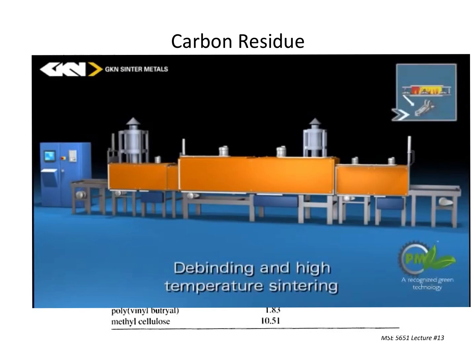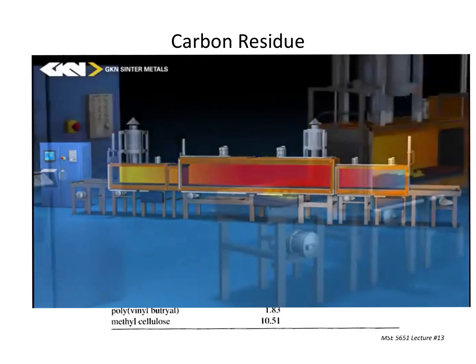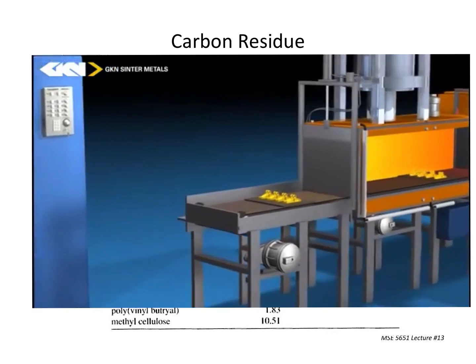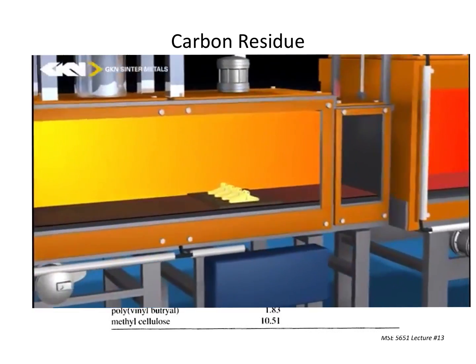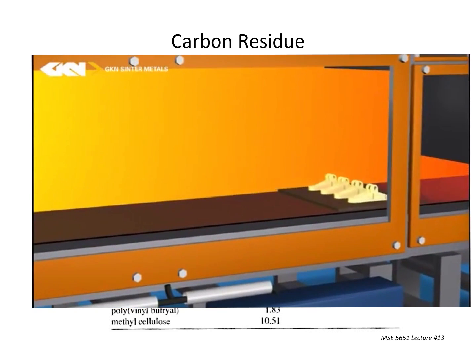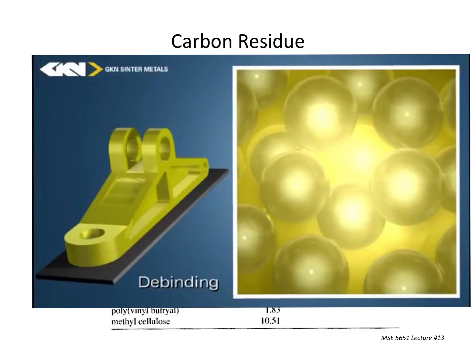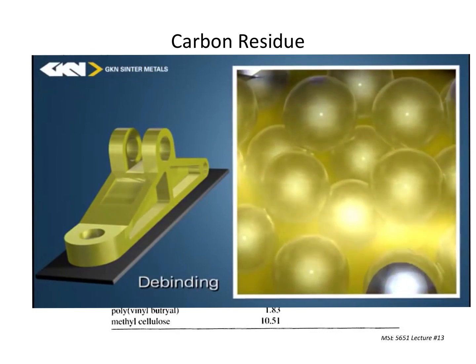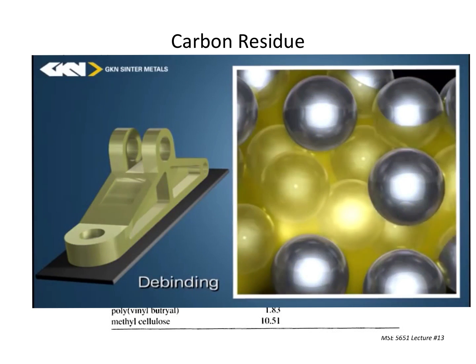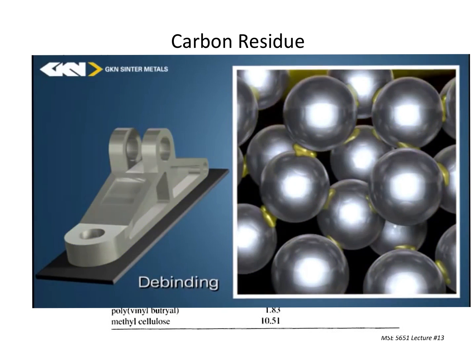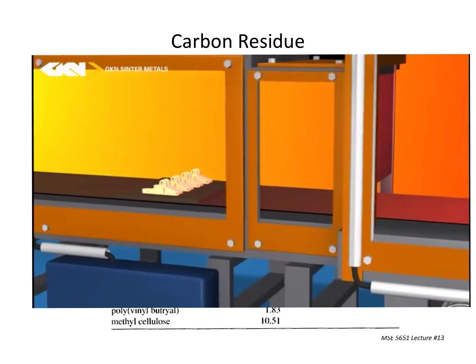And then we go to the furnacing. So you paid someone to take off the runners and the gates, the screws, and then they bring them over and they load them in the furnace. A nice neat line in this case, even more than that in reality. And so you see the initial debinding stage in which we're looking at removing the wax, and we'll see that in a minute here in more detail. And then what's left behind is the polymer. So this is what it looks like post-injection molding, bathing in liquid. That liquid, most of which is wax, is removed, but you leave some behind, and that's the polypropylene, the glue holding everything together, without which nothing happens.